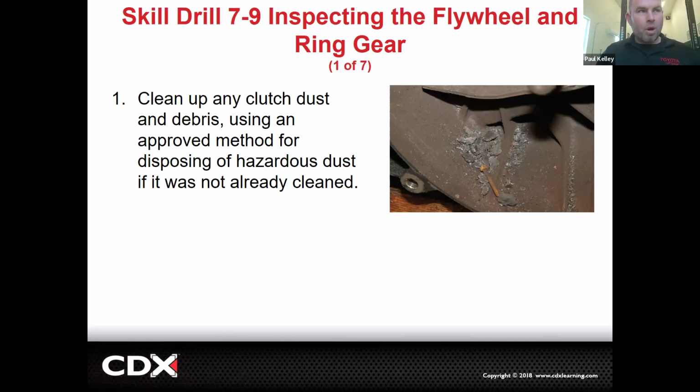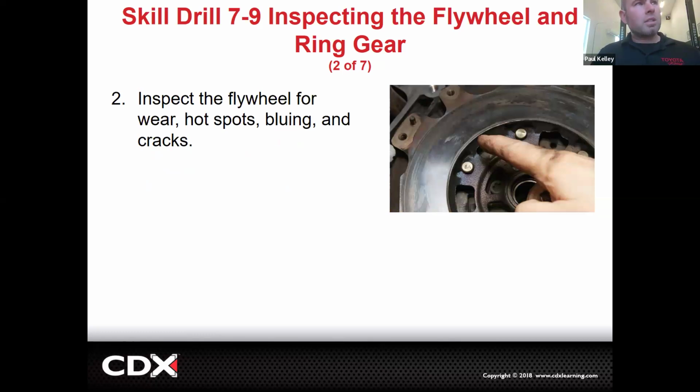But also when you take something apart, you're going to look at that and be like, whoa, something's wrong with this clutch. But if it's from the old clutch, not the clutch you just did, they might be blaming you for something. It was really just something you didn't clean up, right? It's like residual oil after an oil change. But additionally, on some of those parts, we really need to clean this. You can't be having clutch dust on a lot of these parts. This all needs to be cleaned up, especially on the input shaft and that hub, got to be clean. This one, for example, be no-go.